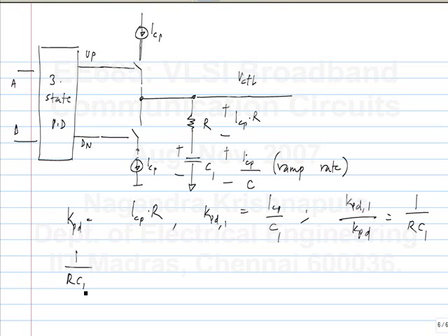So 1 over RC1, which is the 0, is this. Now, the impedance of the capacitor at this frequency is 1 over 2 pi FRF C1, and that is much smaller than R. So if a current pulse at a rate FRF is flowing into the series combination, the impedance of the capacitor is much smaller than the impedance of the resistor. So the voltage across the capacitor is much smaller than the voltage across the resistor. For fluctuations of FRF, it's the resistor that matters; the capacitor is as if it's not there. We said the same thing by showing the loop gain plot and saying that the 0 is much smaller than FRF. But in terms of currents and voltages, this is what it means.